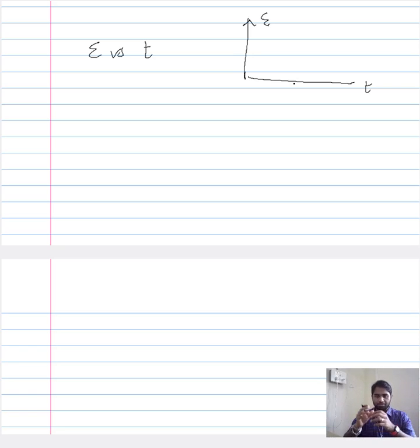However, there might be the possibility that towards the end of your testing, the cross section of your sample might decrease. When your cross section decreases, ultimately that would increase the stress. So even though overall, when you consider your apparatus, you are applying constant load, locally with respect to the material there is an increase in the stress, and therefore the mechanical condition that you assume to be constant is no longer true.